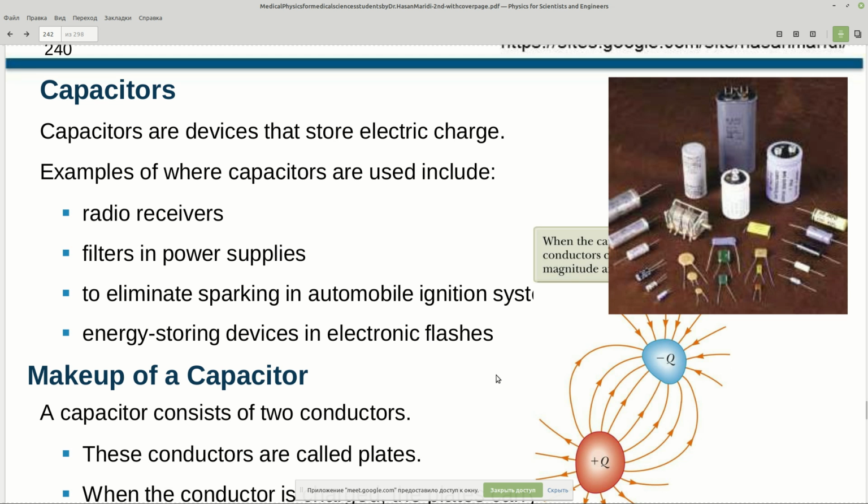Then we take the dielectric capacitors. A dielectric increases the capacity of the capacitor when we put the material between the plates. It also increases the maximum operating voltage. Examples are glass and even waxed paper. The task from the previous time was solved.